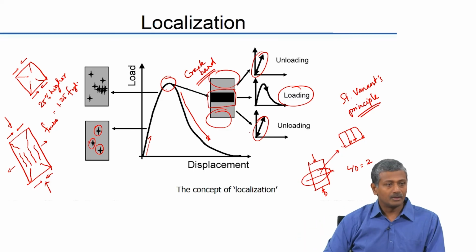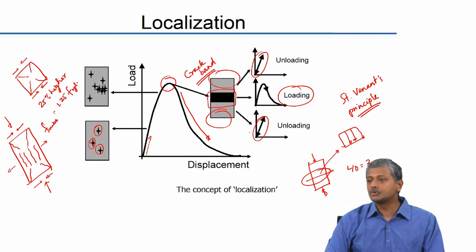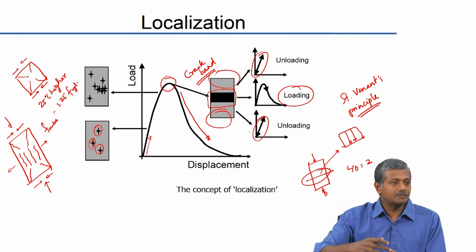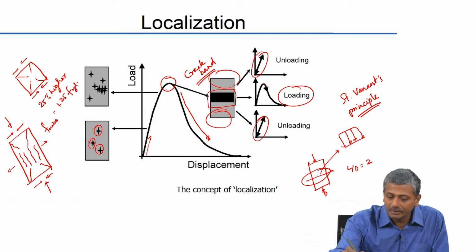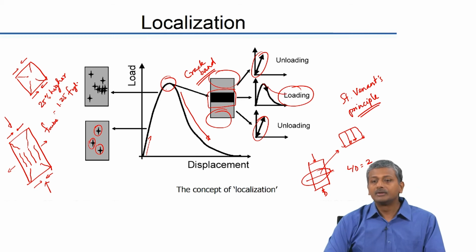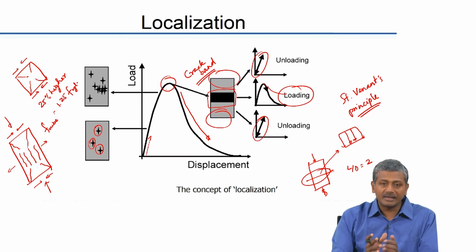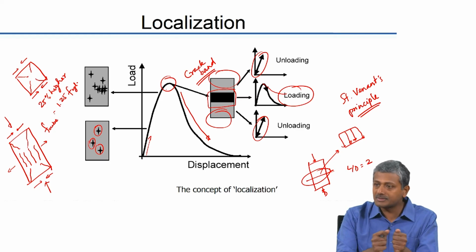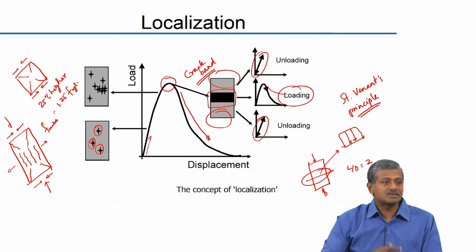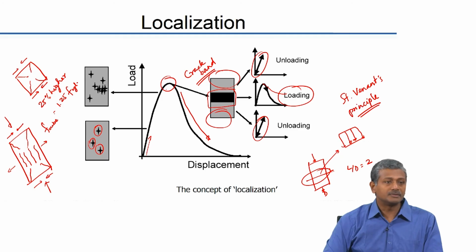that leads to a slow development of the crack length. And this is where we can adopt the use of fiber reinforced concrete. Okay, what does fiber do? It will bridge the crack and prevent the crack from opening up fast. So, instead of getting a behavior like this, you will get a much more slower growth to failure. So, the crack will not open up suddenly. Okay, even in the case of regular concrete, it takes some time to open up, but still with the fiber reinforced concrete, that time can be extended tremendously. So, you can get extremely good post crack behavior.